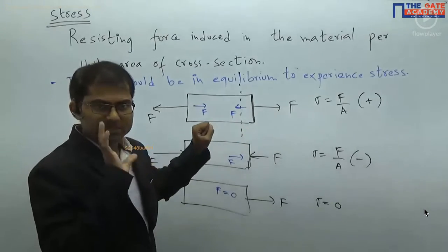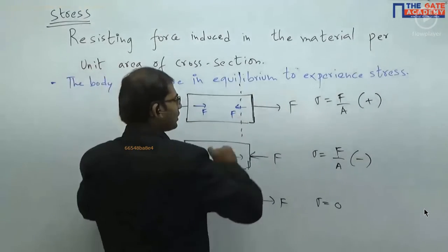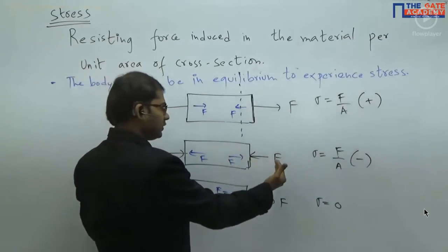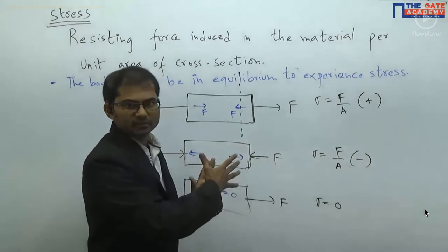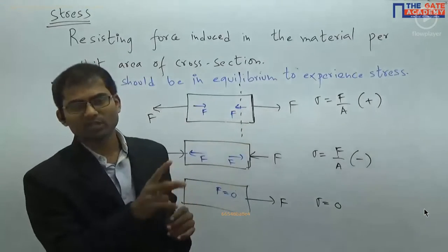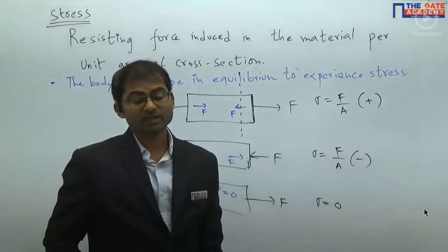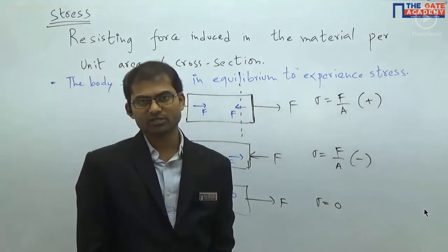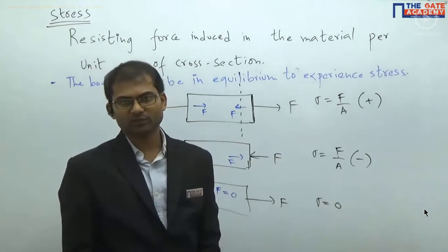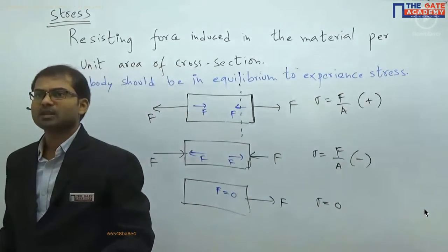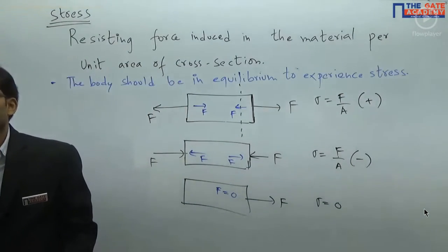Okay. So we'll take the sign positive if it is tensile in type. We take the sign as negative if the external force is compressing the material. Compression and tension both are actually a little bit different in real materials. That means the way the material is behaving for those two loads is different, so we have to distinguish between the both of them. So this negative sign or positive sign will help us. Okay? Am I clear to you, Mayank?